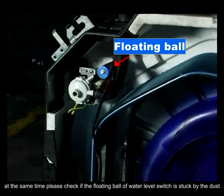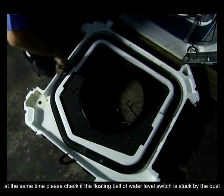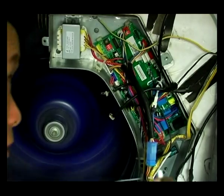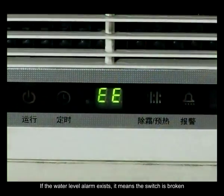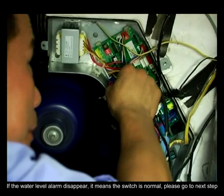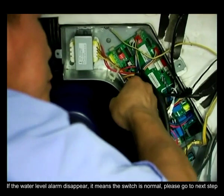At the same time, please check if the floating ball of the water level switch is stuck by dust. Clean the dust in the drainage pan and take off the water level switch. Connect it to the main board of another indoor unit and control the floating ball manually. If the water level alarm exists, the switch must be broken. If the water level alarm disappears, it means the switch is normal. Please go to the next step.